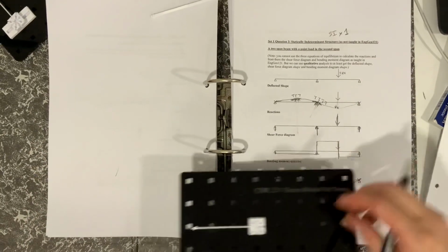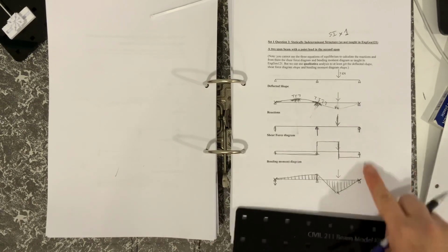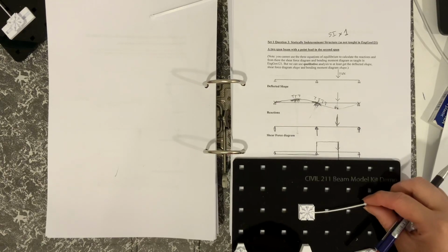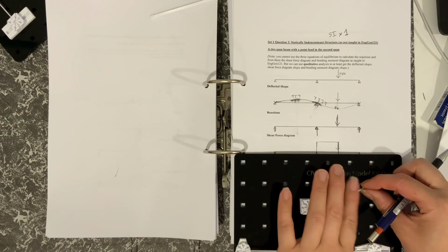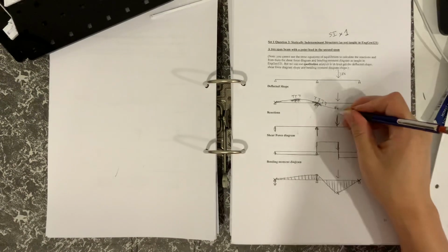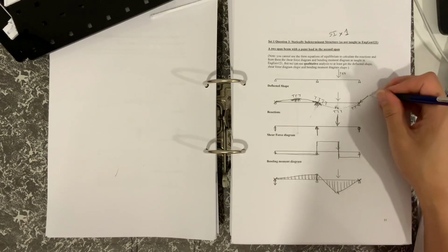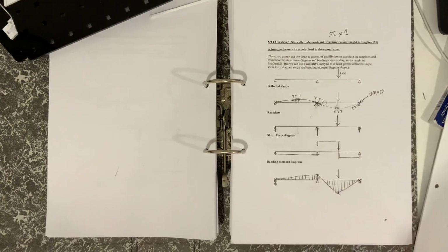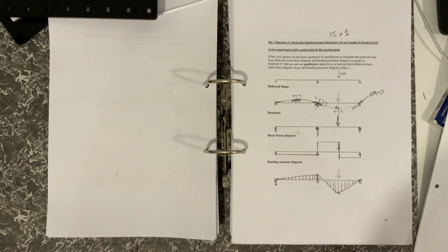So in terms of that one there, upwards, so let's turn that around, upwards, so we've got that going upwards, and that same free body diagram as we move across, so tension on the underside, which is what we've shown there. So tension, tension, tension, tension, tension, and that bending moment would be equal to 0. So that's a 2-span beam with a point load there.